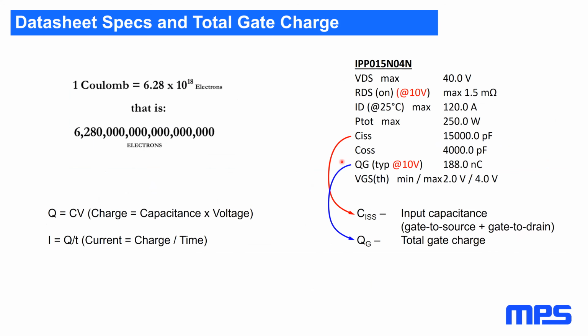One way of calculating that resistance is to figure out how much current you need, which you can calculate based on the gate charge and the amount of time you want to slew. That gives you a current. From there, you can start out by approximating that the resistor you need is going to be the gate drive voltage divided by that current. So 12 volts, 1 amp peak, 12 ohms, right?